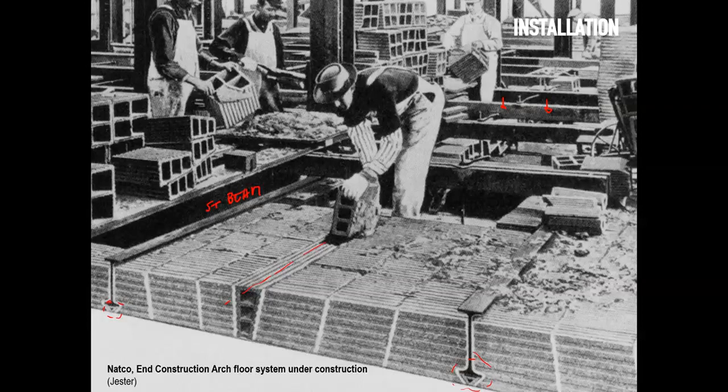So mortar eventually will dry out, and therefore this flooring system, once the mortar is set, will be able to support itself, after which the centering system is removed and the work can continue somewhere else in another bay of the floor. Or it can also be dismantled and then taken up to the next floor using the lifts or using the cranes, and the construction can continue also vertically.